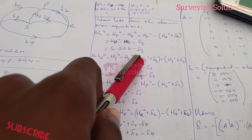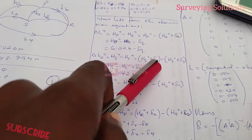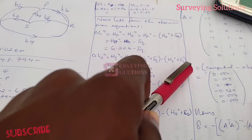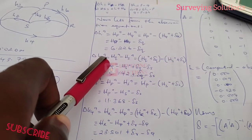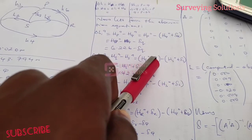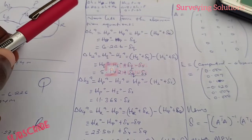So we have the height of q observed plus the error in q, minus the height of s observed plus the error in s, right? So when this minus tries to open the bracket, it will change the height of s to minus, and it will also change the error in s to minus. So we now have the height of q observed minus the height of s, because of this minus has opened this bracket, then plus the error in q, which is still positive, minus the error in s, because this minus has opened this bracket. Are we together? So that's how you carry out the expansion.